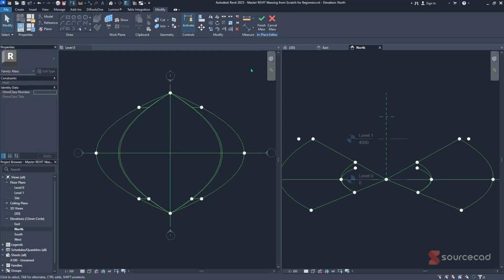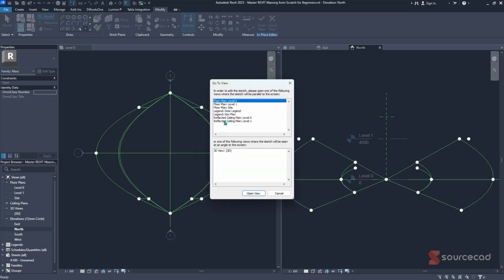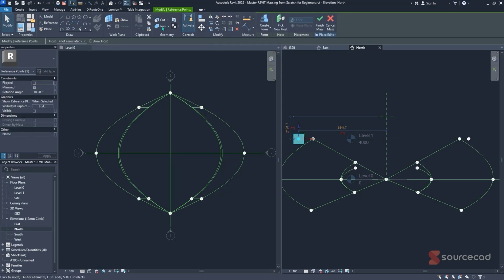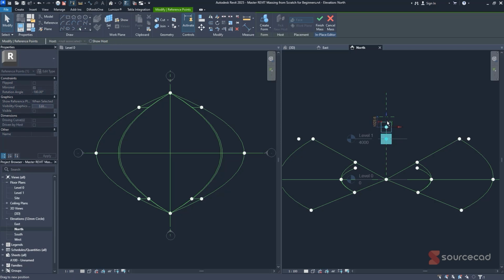Then I'll just place my control point. So I'll click on this point here, click on roof, RF1, then click on, let's say, a specific area that I want. And then all I have to do is just select one of the items that we have here, then click on copy. So I'll click on copy from the center to this specific area here. Then all I have to do is just simply move it. So I'll click on that. Then I can, in accordance to that reference, I can just input my value being 0.